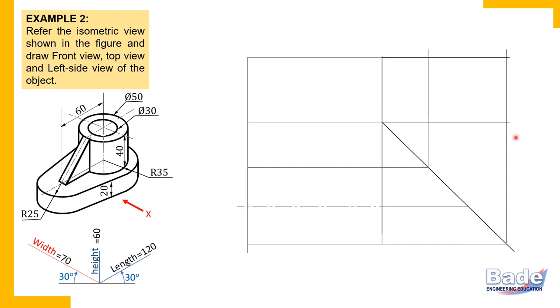Now in the side view also, this is the front side and this is the back side. So front and back, two identical parts we want. So draw the axis of symmetry here. Join the midpoints of these two horizontal edges of the rectangle, or you can draw the axis of symmetry like any other projector from the top view to the side view. Okay, so axis of symmetry.